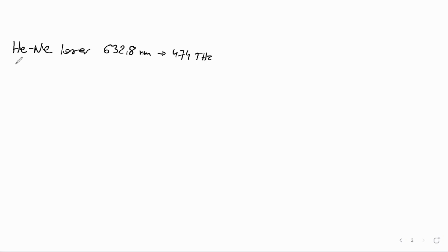So let's assume that our laser has the length of, let's say, 1 meter. This will correspond to the free spectral range c over 2L equal to 150 megahertz.